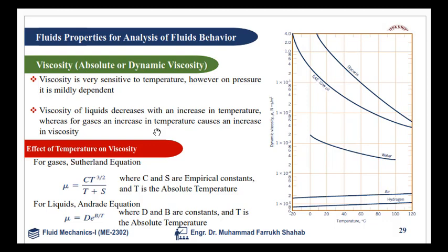So this behavior is actually opposite in gases and liquids, the behavior of viscosity with respect to temperature. We have some relations through which you can find the viscosity of a fluid, which are the Sutherland equation and the Andrade equation.